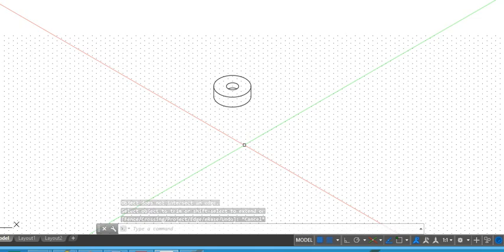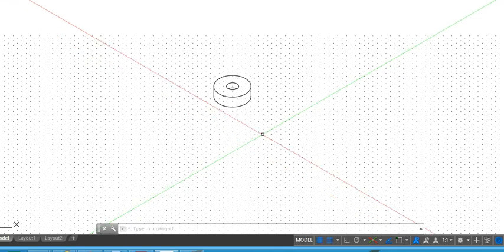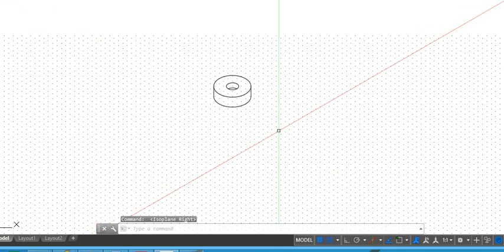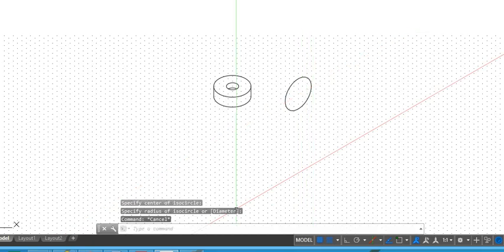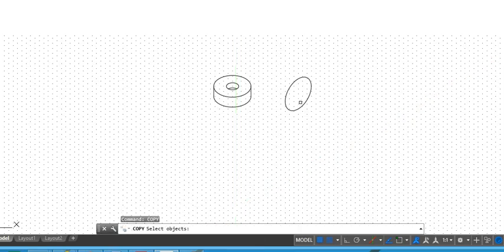So this is a simple case when we have a disk of this shape in the top view. Suppose you want to make it in the front view or side view, how are you going to do it? Let us say we have a right side view, then this is the cursor which will draw the ellipse on the right side. I'll show you how we make that happen. Exactly the same way, we draw 3 grid spaces, and then we copy this.